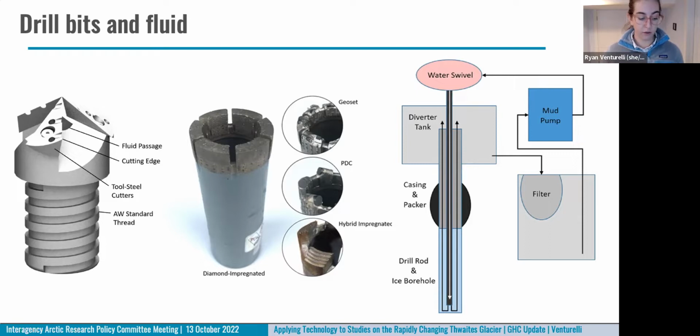The purpose of the drill fluid is really to cool the bit and flush chips away to the surface so that fluid can be filtered and recycled in the closed loop system. And a schematic of that system is shown on the rightmost portion of my slide.